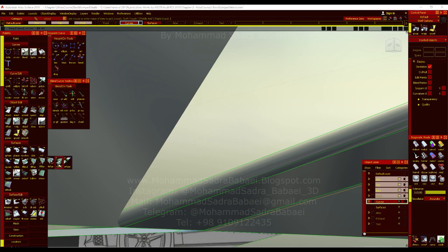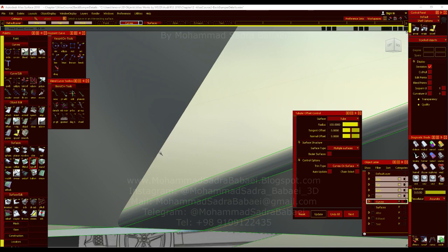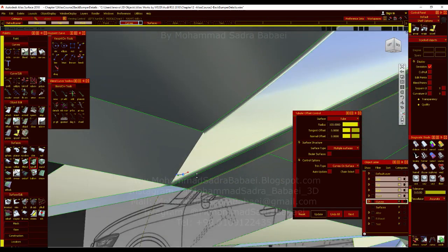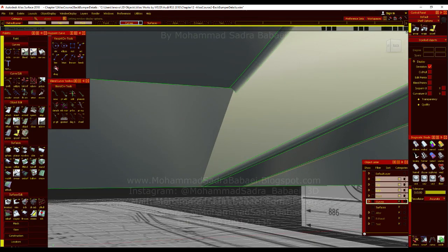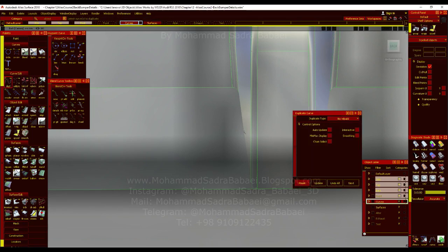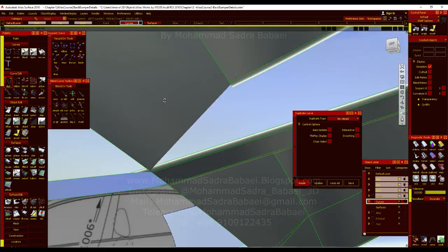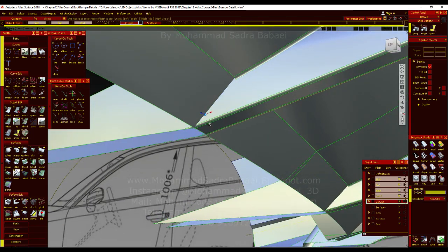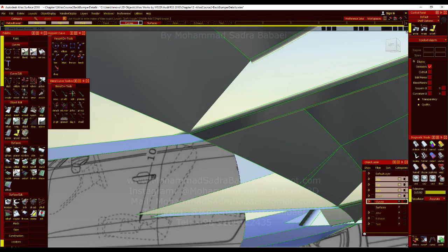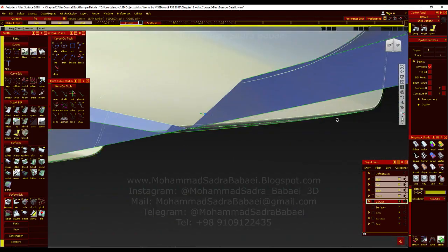I can use tubular offset tool to trim this surface, or I can also trim that manually. So I'm gonna duplicate this line. Let me see, is there any line here or not? No, so we're gonna intersect and trim it again. Just intersect these 2 surfaces from that initial surface.